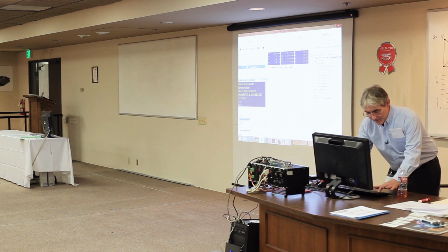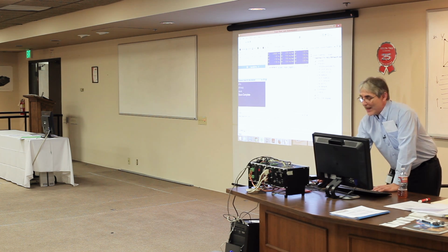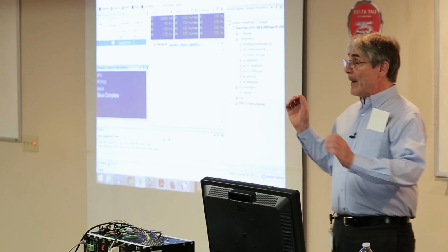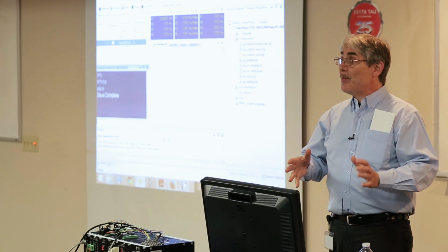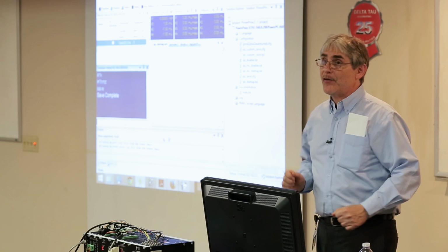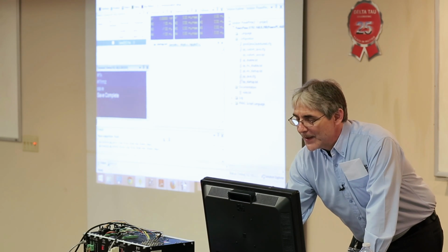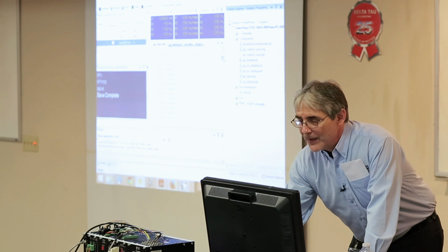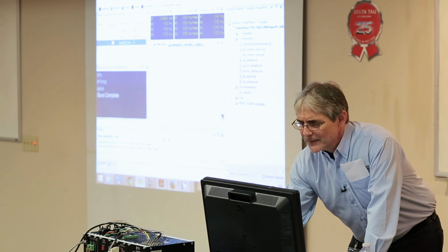If I do a save, by doing a save now, what I've done is, if you remember, every time you type save in the IDE, that takes everything that's been saved in PowerPMAC and puts it in the ppsave CFG file. And so now I can go over here and I can open up the ppsave CFG file that was just modified. I can go down and find my compensation table.